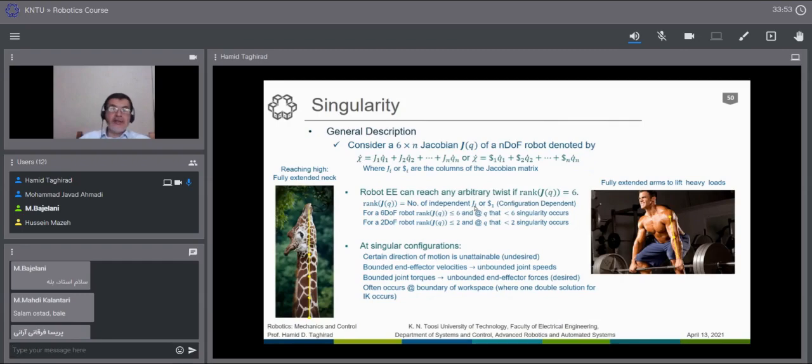So if we have 6 independent screws, then the determinant is not equal to 0 and we have an inverse. And we remember that the screw axes have some physical and geometrical properties, such as direction. You can plot them on the robot: the direction s hat and s0 hat, and the distance between this direction and the 0 axis.